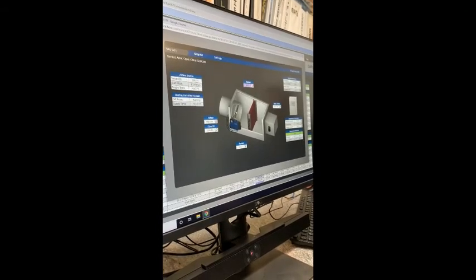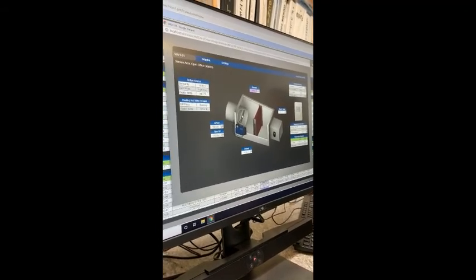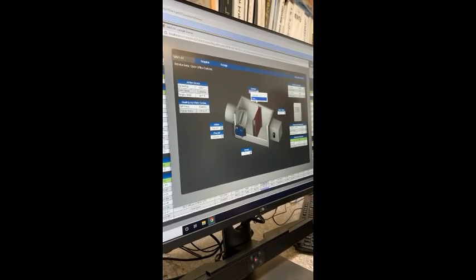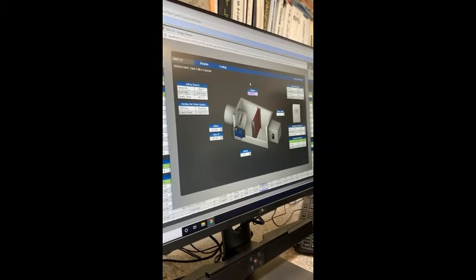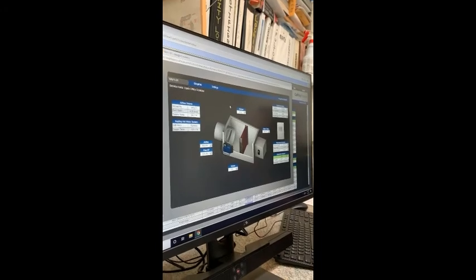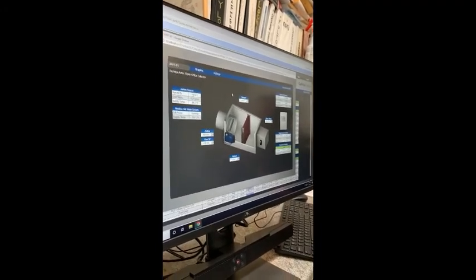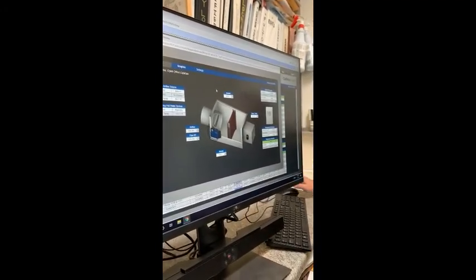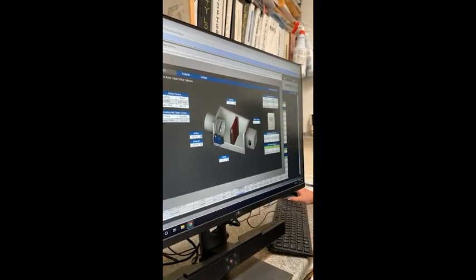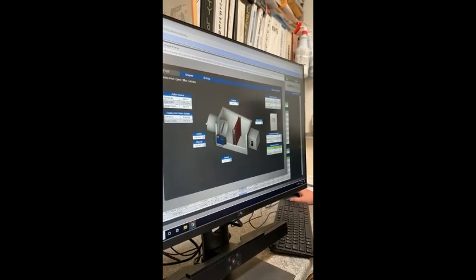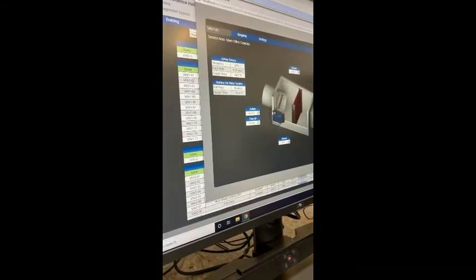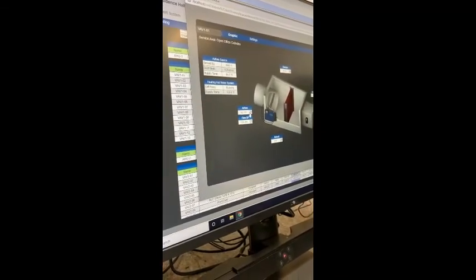But this point here is actually based off of the damper position, which is a dynamic feedback that the controller determines based on basically steps. It will zero out every once in a while, and then it keeps track of where it is and knows. But if those values aren't matching in a certain time, it would show an alarm and shoot to the alarm console. You would also get an alarm, most likely, because the airflow values would be off, and that would also send an alarm.